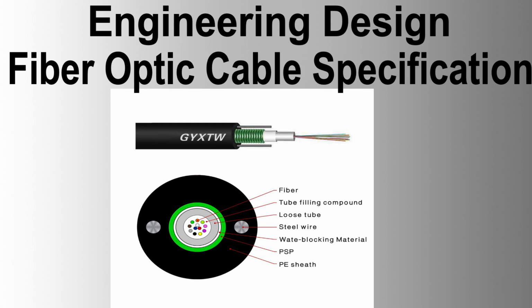Fiber optic cable tests. General. All type tests and routine tests shall be carried out as per the relevant standards, and all certificates and test results shall be made available for evaluation and acceptance. The contractor shall provide the testing and calibration equipment necessary to test, calibrate, service, and generally maintain the system equipment to its maximum reliability and accuracy. The company reserves the right to witness all the tests and must be notified at least 20 days in advance of when such tests are to take place.